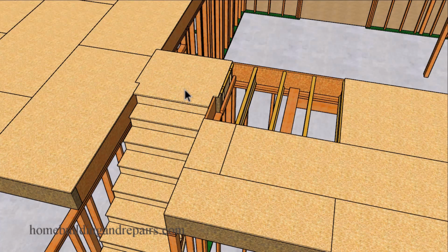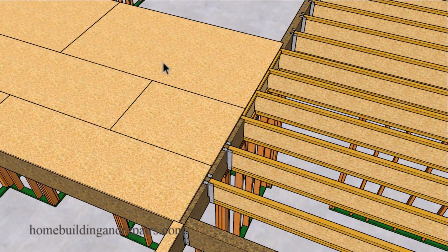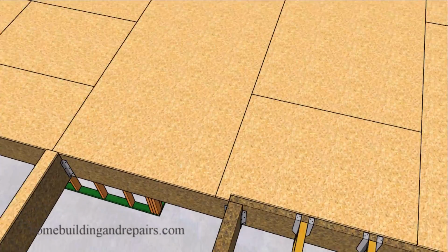Sometimes the floor sheathing will break over here and you'll need to add a block under the floor sheathing or reposition one of the stringers underneath the break. And if you did something like that incorrectly, you could end up with a squeak in the floor here. And of course, the floor sheathing switches directions only in this area here and the two areas in the front,